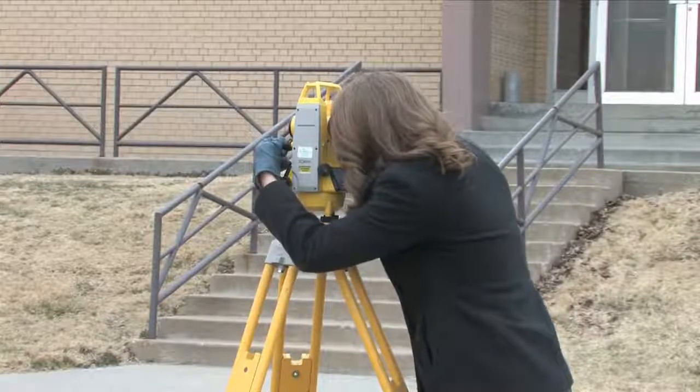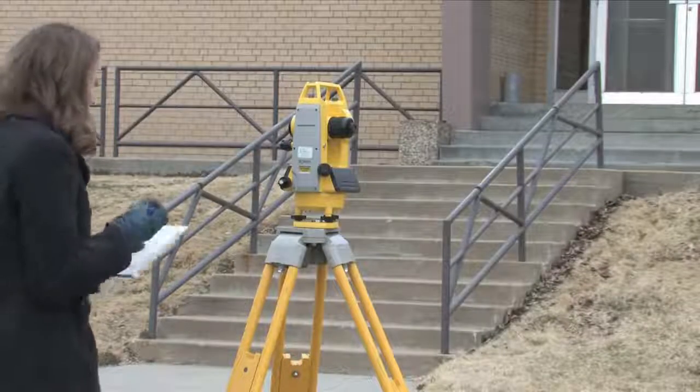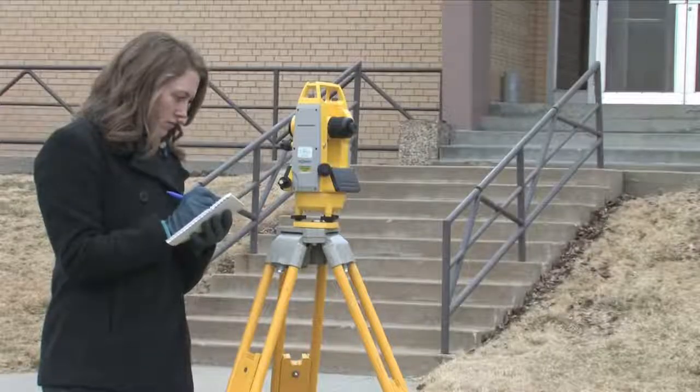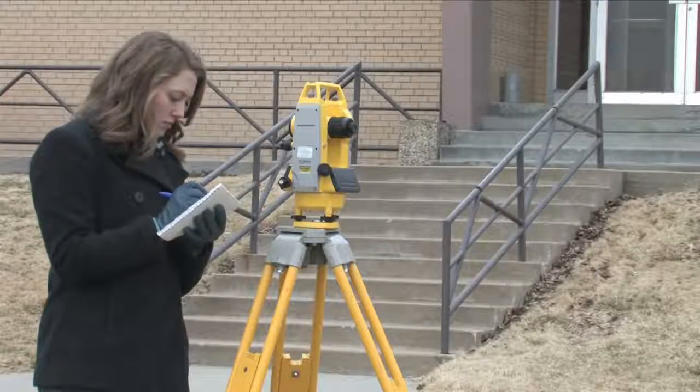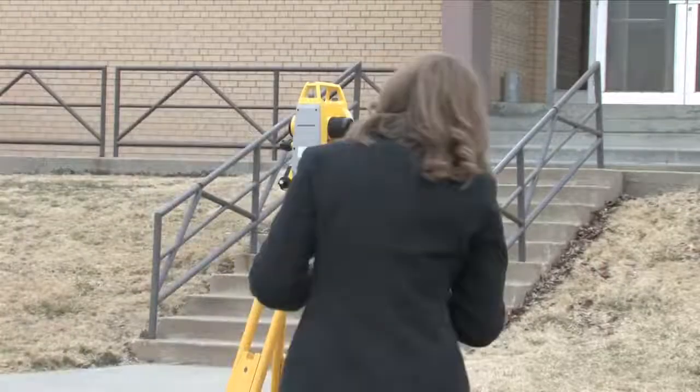Once the instrument is fully sighted in on the HI, the vertical angle reported should be approximately the same as before. Proceed to lock the instrument and record the horizontal and vertical angles, as well as the upper and lower stadia readings at point B. Remember, this is a plunged horizontal angle.